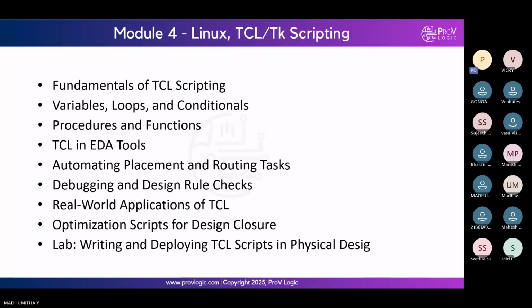Where do we use Virtuoso and Power Compiler from Cadence and Synopsys? We will be using these to fix IR issues, IR drop and EM issues, and also if we are running a low power design. Sometimes the clients will come with specific specifications like, I don't care about the timing or area, but the power incurred in my design must be very low.